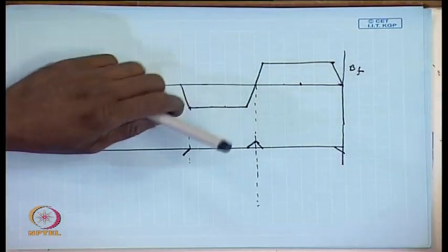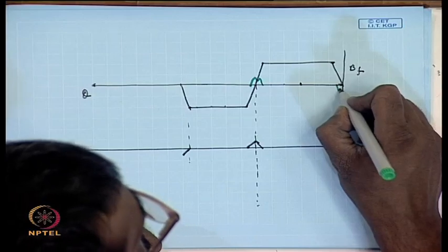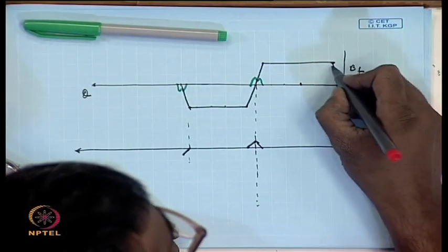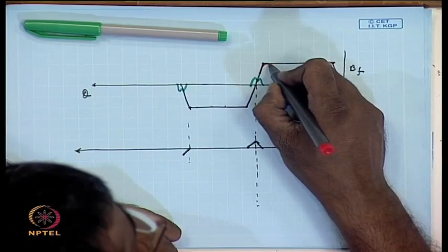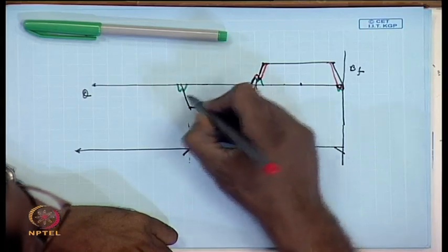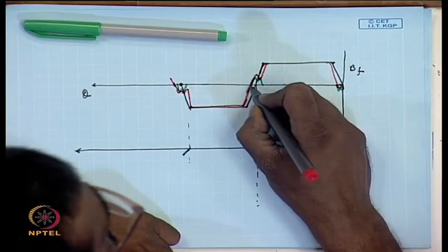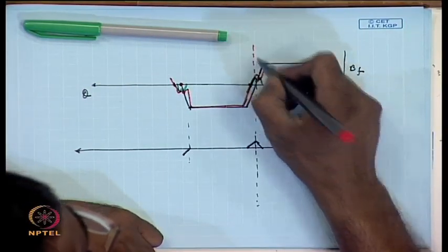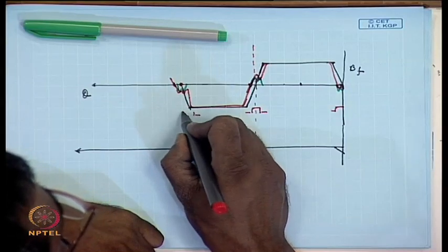Hence, there will be small armature MMF flux produced in the interpolar regions, and the resultant flux density will still show a shift of the magnetic neutral axis, that is, the position where the brushes are normally kept will not have zero flux density.